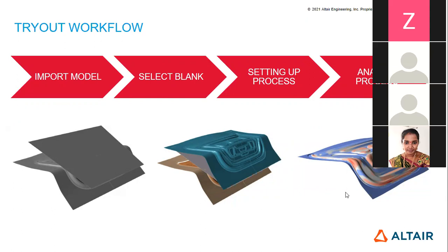Their thickness you can also vary. Suppose the steel portion has a thickness of 1 mm, and the brass or copper portion has a thickness of 1.2 mm, and they are welded together. After the welding, you put your blank into the die for forming. That is known as a tailor welded blank. So select the blank, whether it is single or tailor welded.